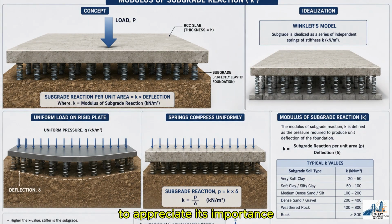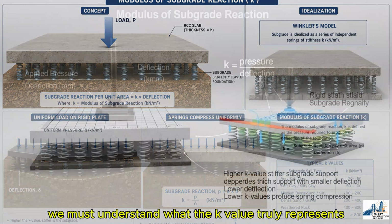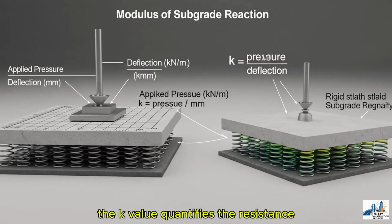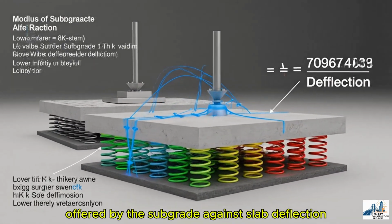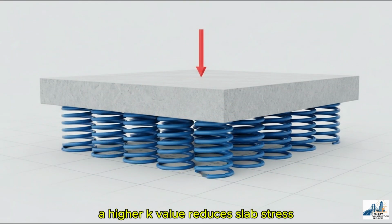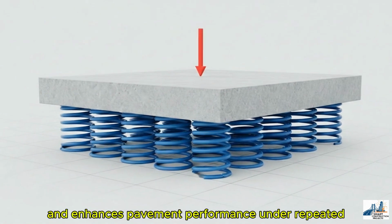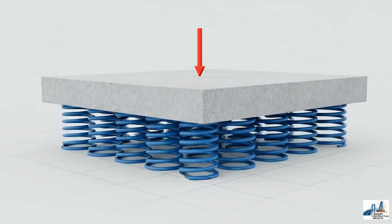To appreciate its importance, we must understand what the K value truly represents. The K value quantifies the resistance offered by the subgrade against slab deflection. A higher K value reduces slab stress, improves fatigue life, and enhances pavement performance under repeated heavy loading cycles.